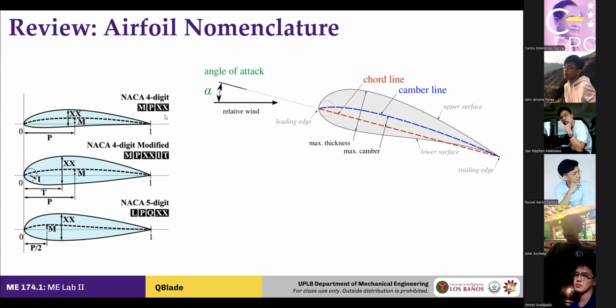So, yung mga airfoils sa NACA, they usually start out with the label NACA, then 4 digits. Yung first digit, this would be the maximum camber. So, the max camber of the airfoil. And yung second digit would be the location, respective to the leading edge. So, kapag narinig niyo yung term na 4415, so that means yung max camber mo is, I believe, 0.4.